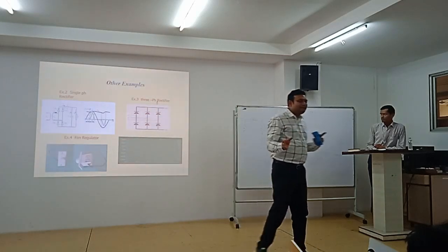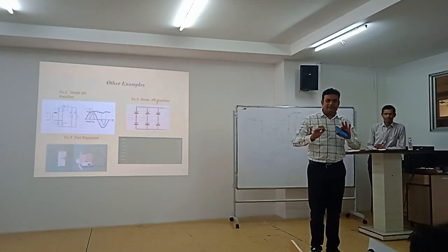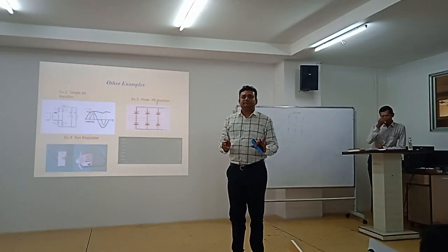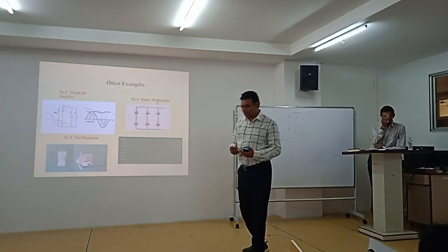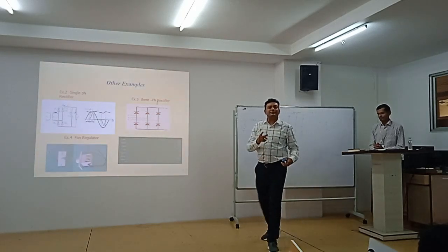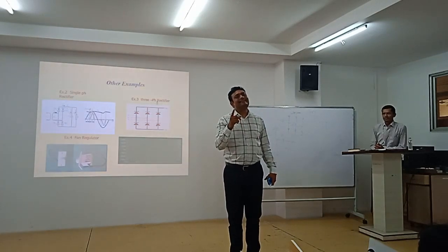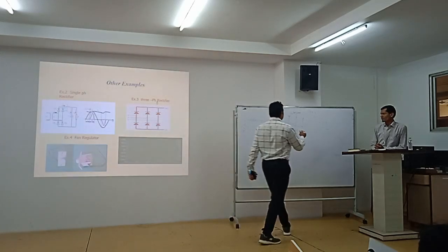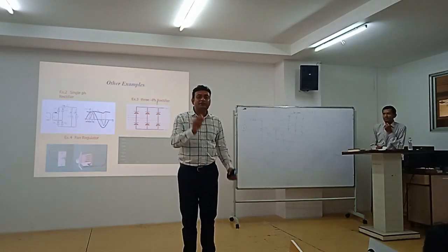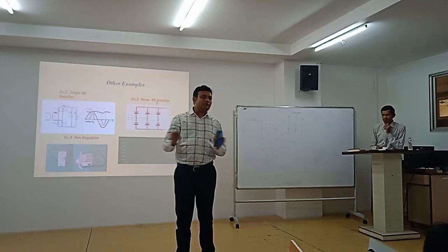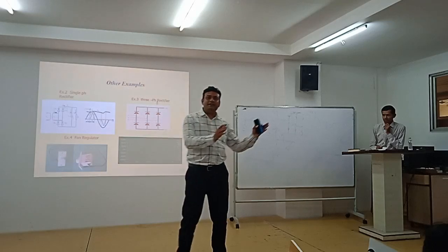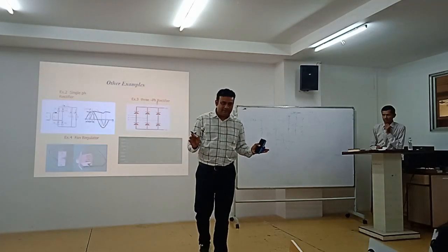What is the nature of the output of a fan regulator? What is the output of a fan regulator? Variable voltage. Is it RMS voltage or average voltage? If you say average, it becomes 0. For any cycle of AC, the average is 0. We are specially defining it in terms of RMS. So whenever there is the output of a fan regulator, you have to call that voltage RMS voltage only. Right? Whether it's 20 volt, 40 volt, 48, 230, it's RMS voltage. It's not average voltage.